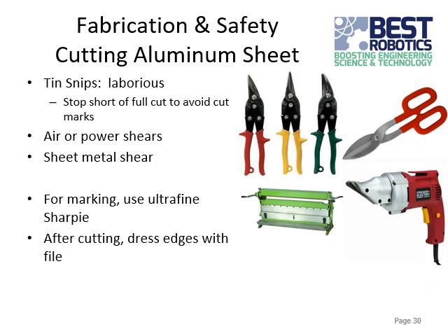For the aluminum sheet, because that's going to be a really wide and thin sort of thing, you're probably not going to want to use those tools I just talked about for the bar and the rod. For this, you probably want to use something more like tin snips, if you have them. It can take a little bit of time to work your way through it, but it should work. It might bend or deform the edges a little bit as you cut, but you can make it work.